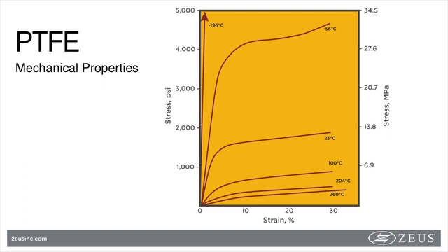However, at negative 196 C, the material exhibits very typical characteristics of brittle materials, where there is not much elongation change in the material upon applied stress prior to its fracturing. Furthermore, at elevated temperatures, up to 260 C, PTFE has a tendency to become more elastic, losing its tensile strength. Nonetheless, the material remains intact and continues to possess useful mechanical characteristics.